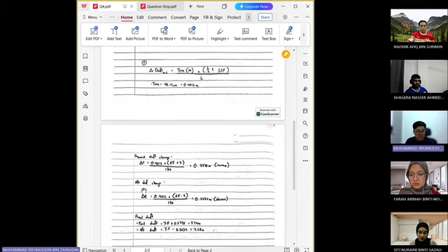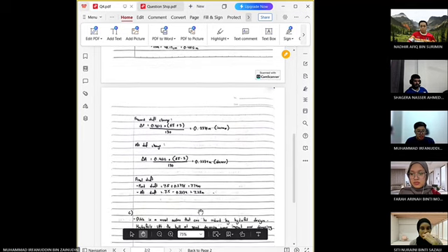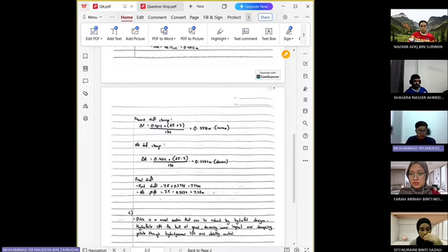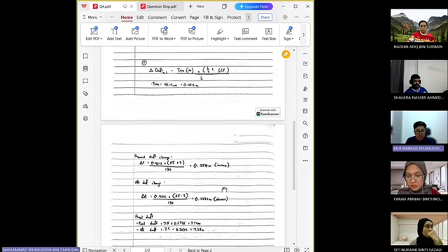And next, for the aft draft changes, also use the same formula with 0.4612 times (6 minus 2) divided by 130, and you get 0.2234 meters, the draft decrease at the aft of the ship. And you'll get the final draft of the ship, depending on the answer, the increase or decrease.